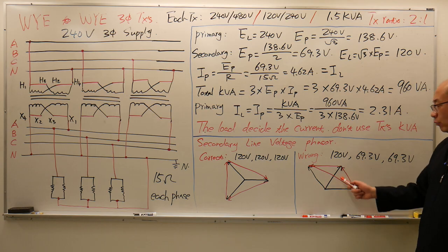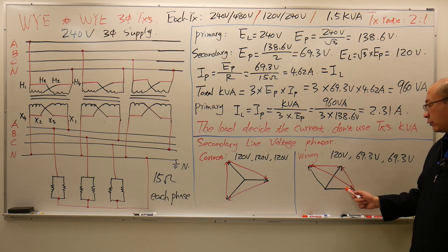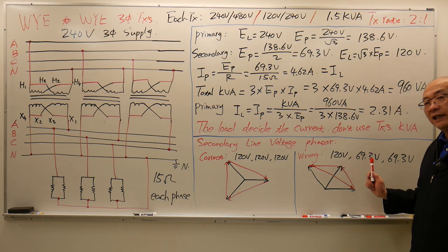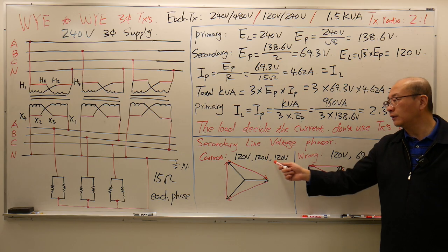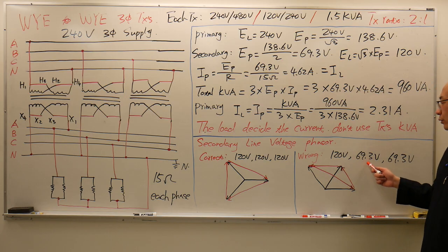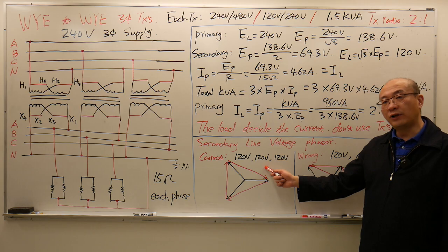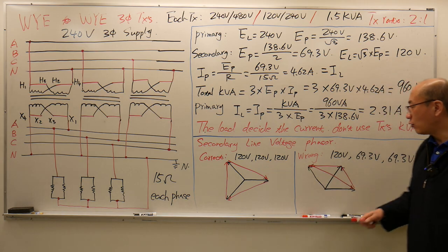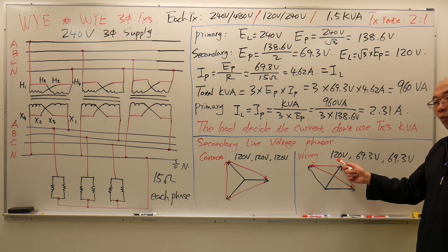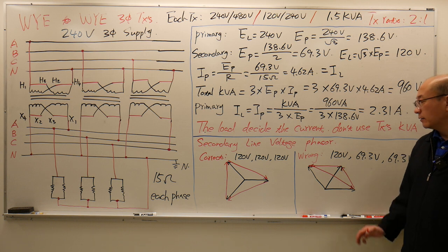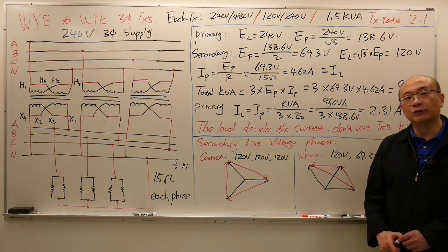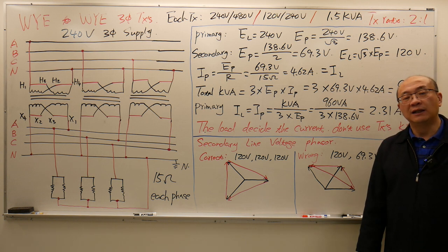Because when I flip it, it becomes 60 degrees here, 60 degrees here. It's an equilateral triangle. So instead of reading two line voltages, I read the two phase voltages down here. So right connection, three balanced line voltages. Wrong connection, you only read one line voltage, and you're going to read two phase voltages. So here's the calculation I showed you. I'm going to go to the lab bench to show you the lab measurement.